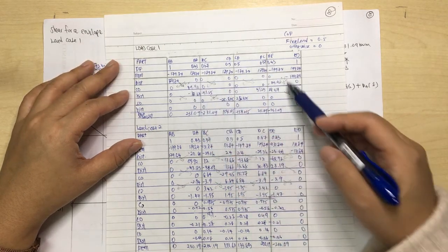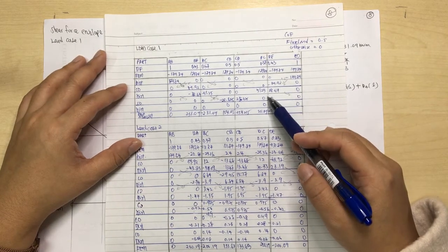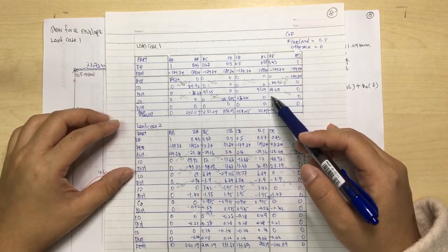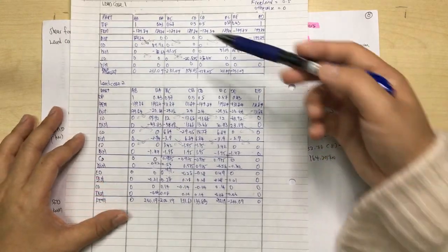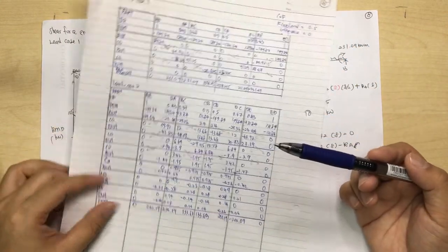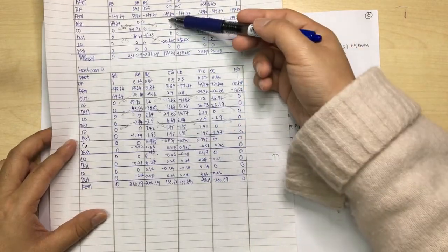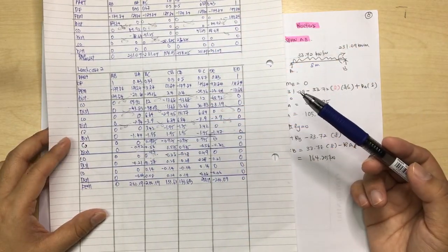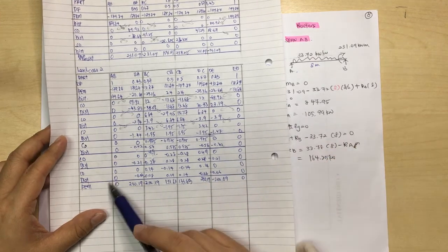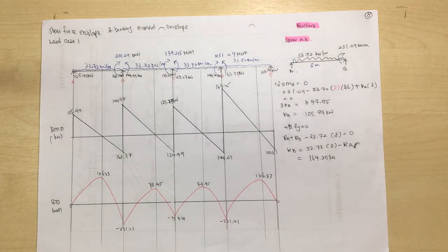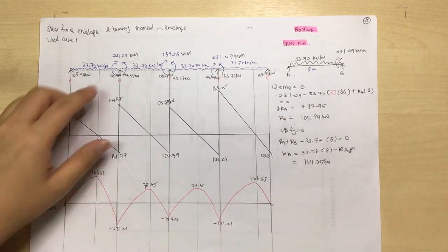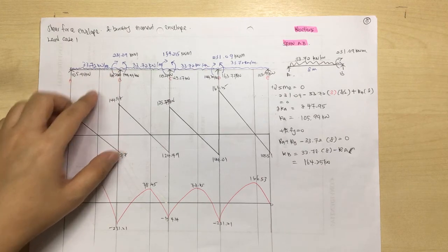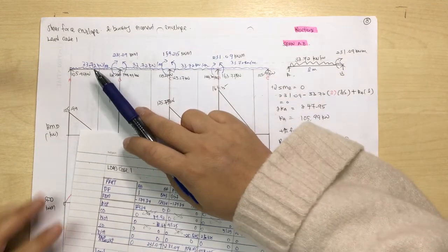I will not explain this at length because you supposedly learned it in the previous subject, and you can refresh it yourself. Also for load case 1, load case 2 and load case 3, you need to repeat the same thing using the modified moment distribution method, and then you get the final moments. After that, you draw the beam again with the W here.